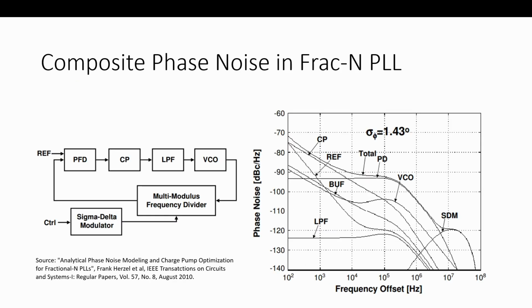So here, in terms of the benefit, being able to make the loop model and come in and out as any node and predict the total noise of the output from all your sources. It's great for that. This is an example, we won't go through in full detail, but this is a fractional N delta sigma modulator frequency synthesizer where you can have a loop model and you have many noise sources. That's what these are showing, is the transfer function of each possible noise source.